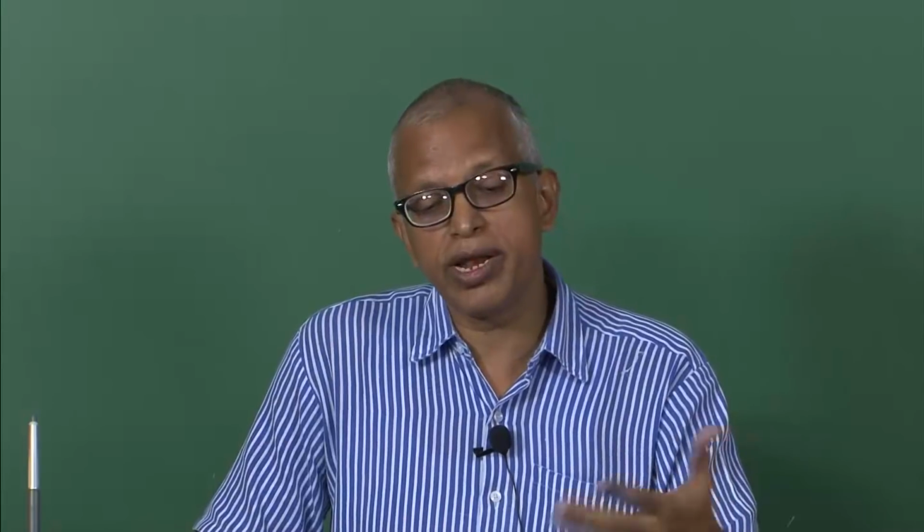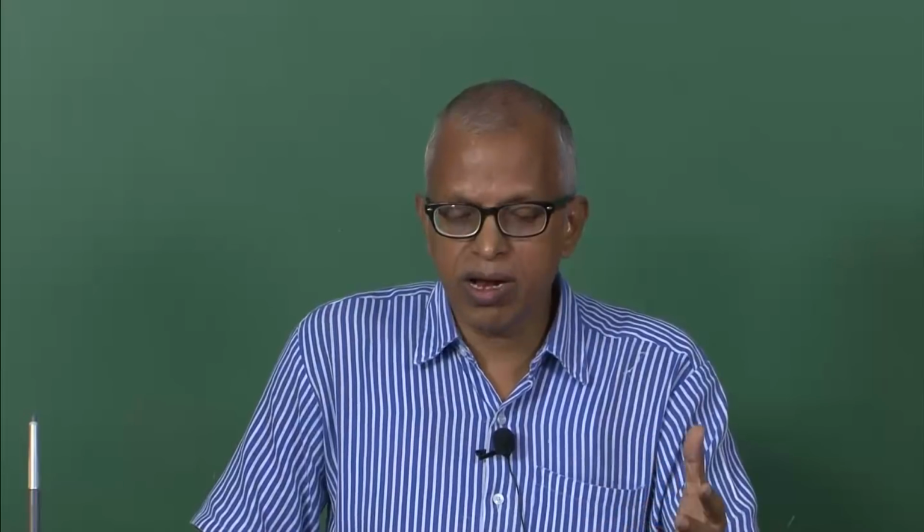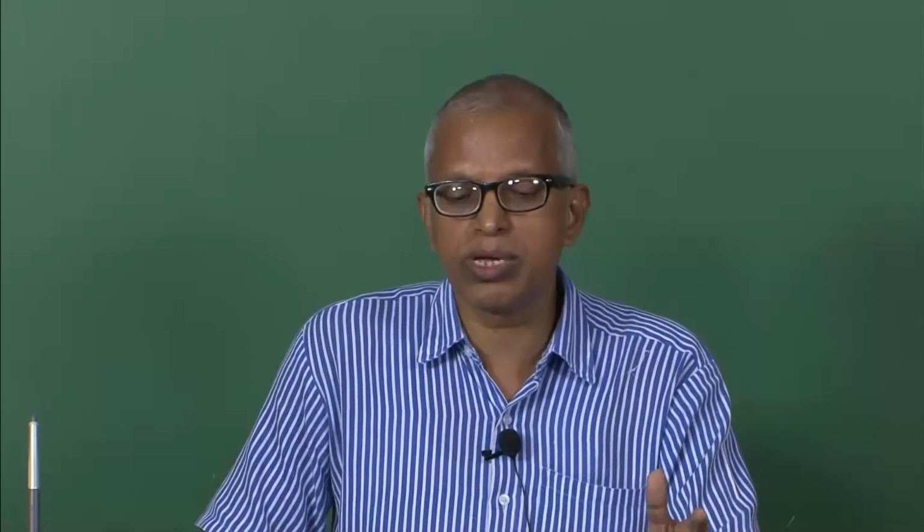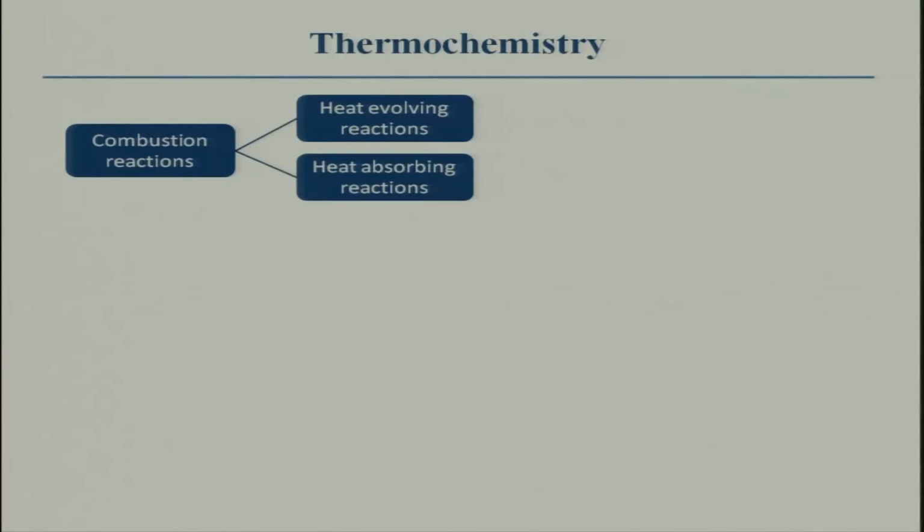So, in the last lecture basically we discussed how to handle the mixture fraction, or the fuel ratio, particularly when we are handling a diffusion flame, and we defined a mixture fraction. We also related that to the equivalence ratio. And I also told you it is a conserved scalar which has a lot of ramifications, particularly for diffusion flames, which we will be discussing later on. And now we will continue with how to look at these combustion reactions, right.